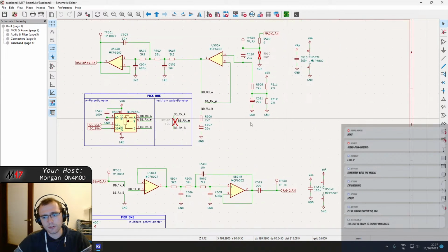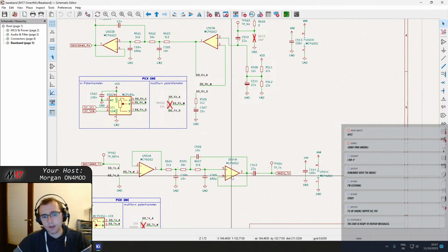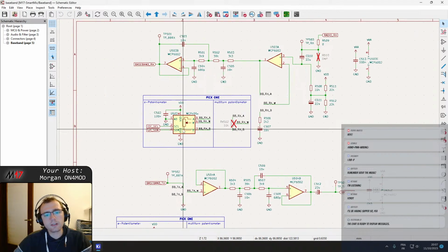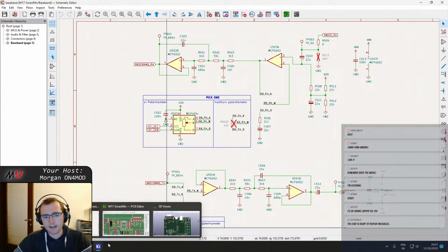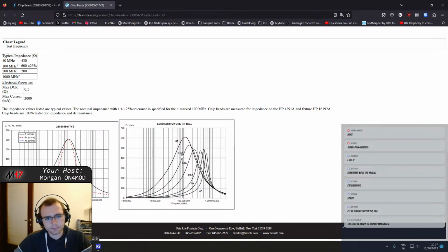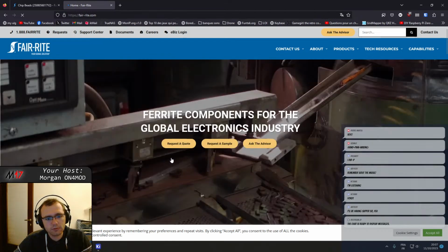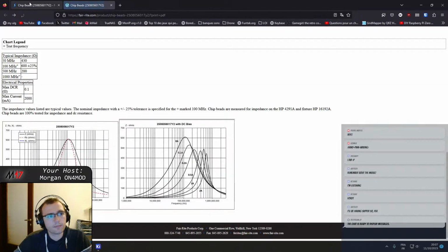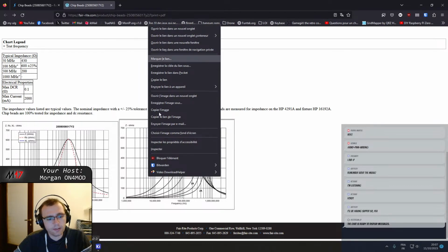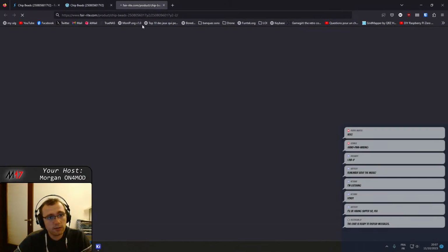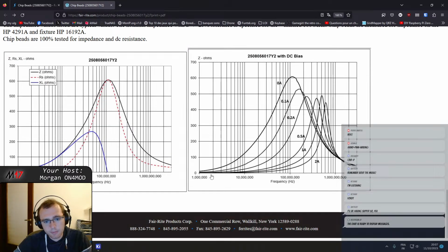The baseband amplifiers are powered via VAA2. But that means that this doesn't consume much, I think maybe 10 milliamps, something like that, so very little current. So it's going to be between those two curves. And you see that the graph starts at 1 megahertz, and at 1 megahertz, impedance is extremely low. Oh, can I open this? No, it doesn't want to. Okay, maybe I can just zoom in.